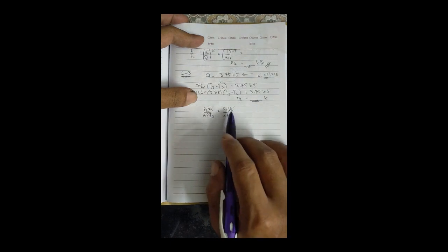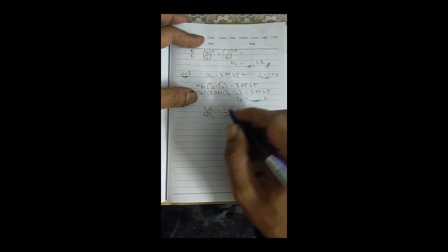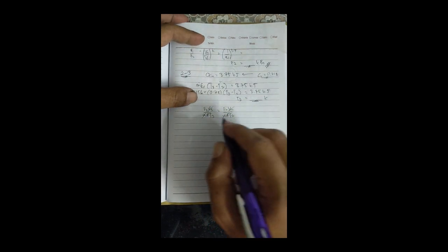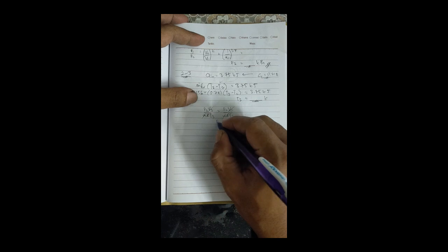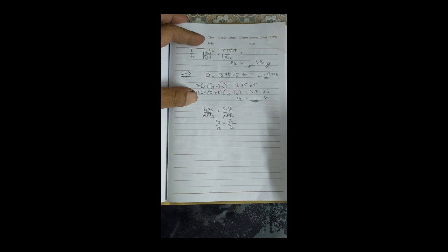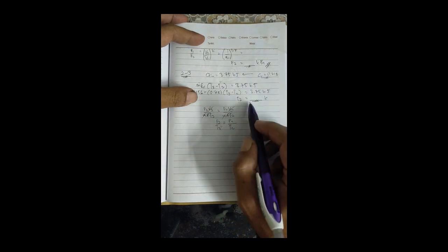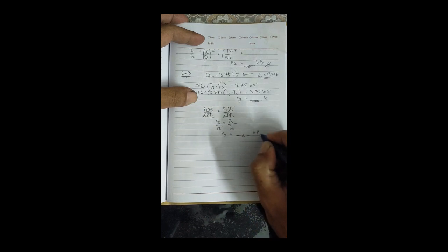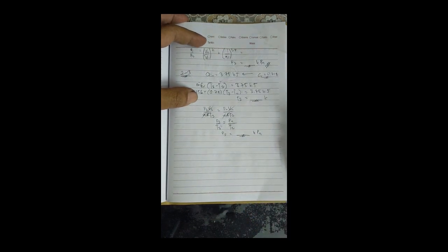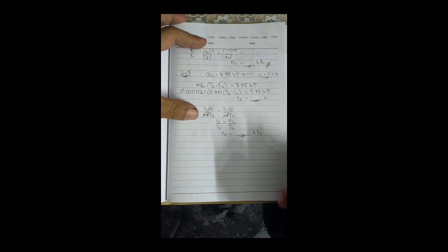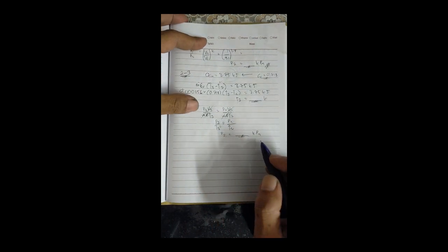Process 2 to 3 is constant volume, so V cancels out, R is similar so it cancels out, and m also cancels out. We are left with only P3, T3, P2, T2. So P3 we have calculated, in kPa. So 2 to 3 we have finished.